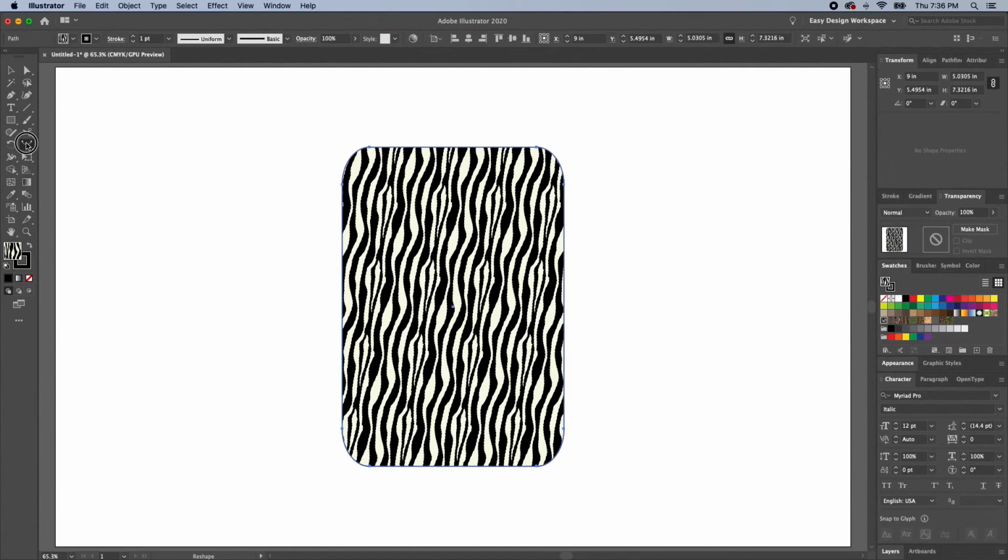All right. The next tool we have to go over in this tool set is the Reshape tool. This is great if you are wanting to quickly put together a mock-up of some kind of form, and you just want to be able to throw it together pretty quick. And let's say your form starts with a square or a rectangle like we have here. So basically how it works is you just select your object with the Direct Selection tool up here. The shortcut for that is A. And then you can come in and you just click and drag, and you'll see if you hold Shift, it's going to hold it constrained to that plane. If you don't hold Shift, then you've got room to adjust it wherever you like.